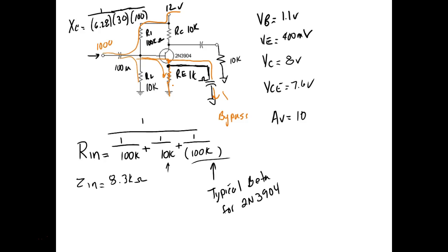Now, of course, when we calculated our voltage gain, we used RE, but now the AC signal is bypassing RE. So RE doesn't even come into play anymore, right? You understand that? So how do we get the gain? What does the AC see? Well, the AC sees the dynamic resistance of a PN junction, which is very, very low.